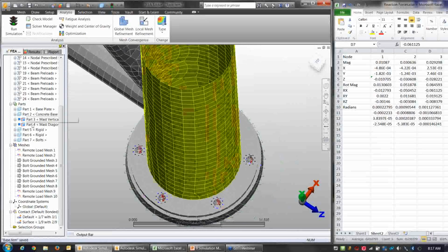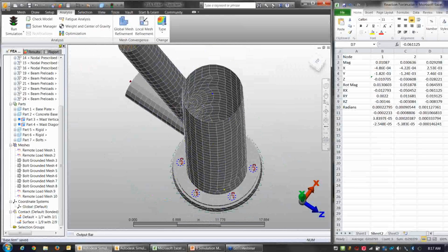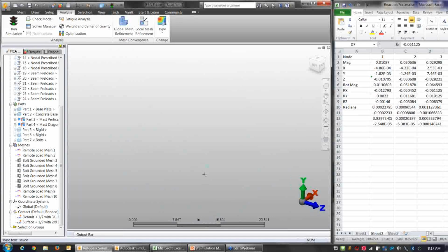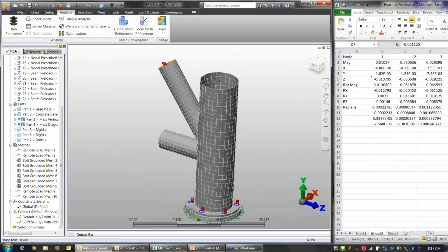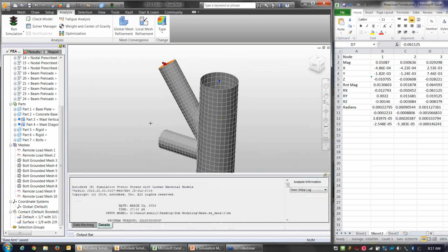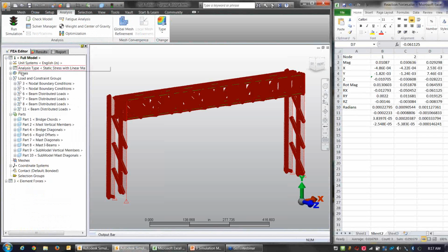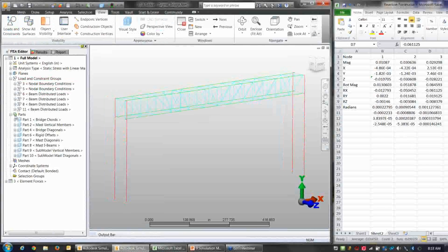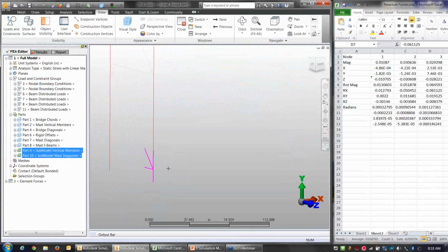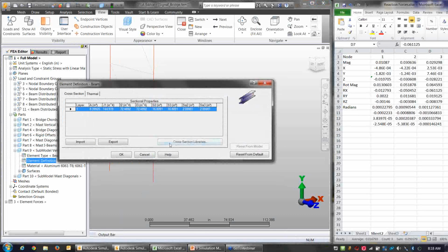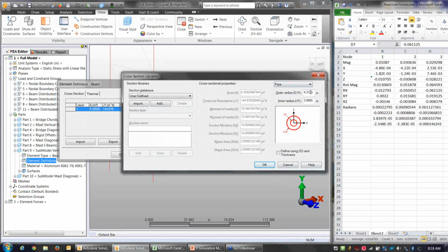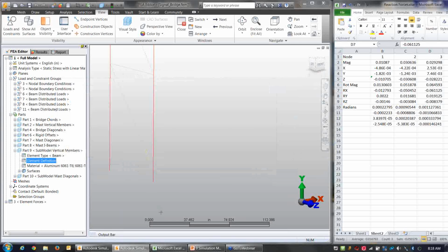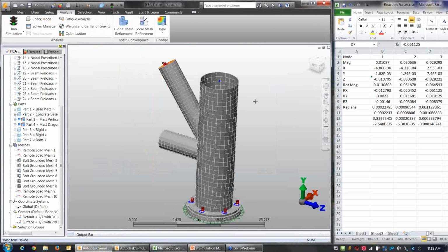This is a new CAD model here. I had to create a new CAD model with the representation of the beam elements as surface geometry and some solid geometry. The solid geometry is additional. This is just surface geometry. I simply extracted that from the definition of the parts in here. So, for example, I had already split off the section I was interested in to new parts to make it easier for me to isolate them and grab the nodes. But basically, I just went in here, used the dimensions here, went into Inventor, modeled the new geometry, and created a new analysis.